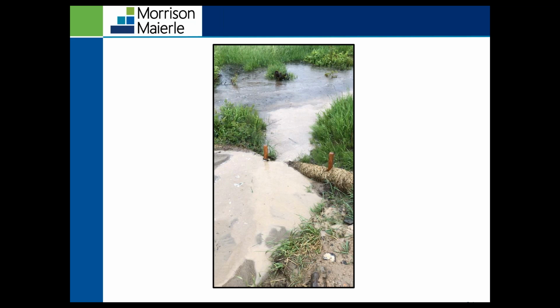And something that's interesting about this, this was a project that I was a SWPPP administrator for. So I had to submit a non-compliance report to DEQ since sediment was being discharged into the water body here. So as part of this permit, to be compliant, you'll have to submit non-compliance reports to DEQ if you're not compliant with the general permit.